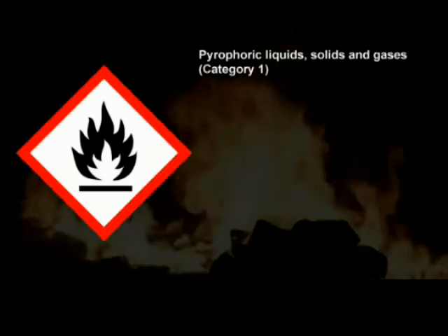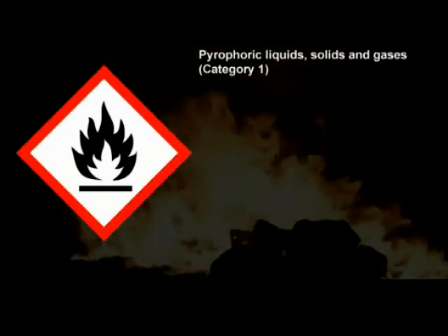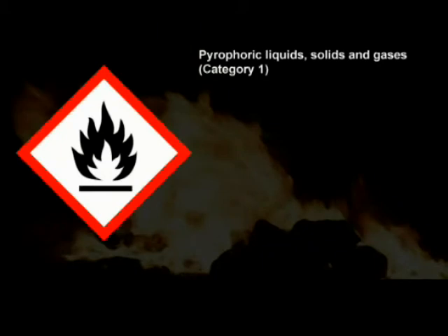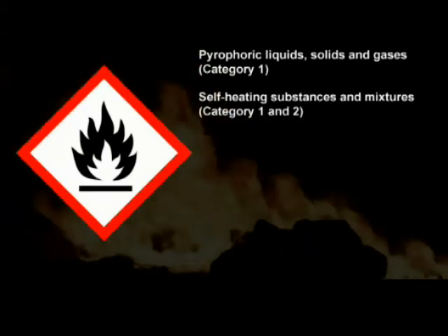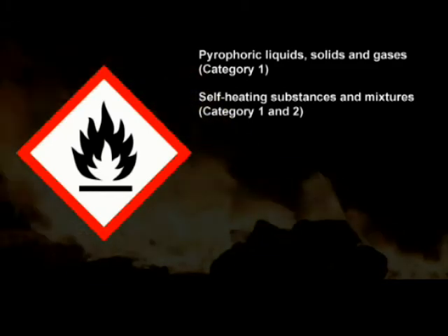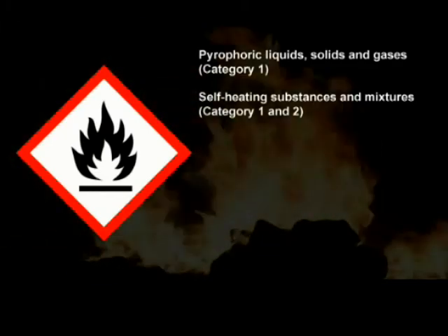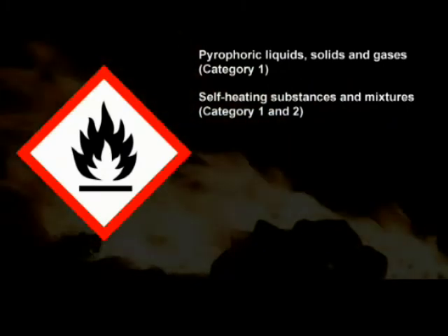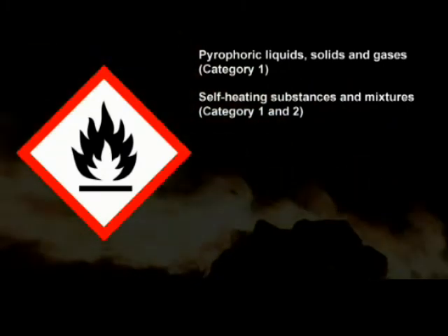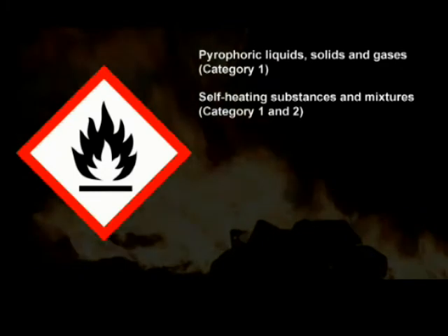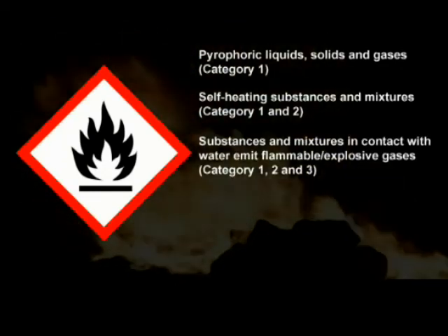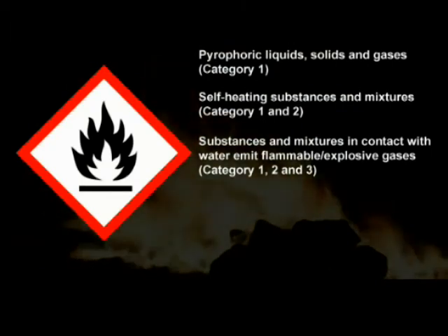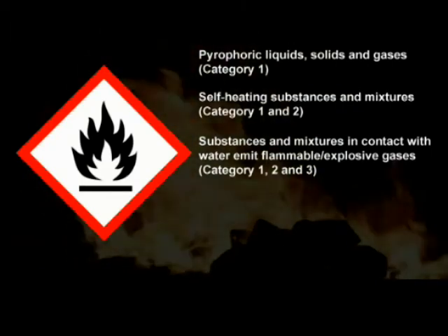or explosion. Pyrophoric liquids, solids, and gases, Category 1. These products can catch fire very quickly, spontaneously, if exposed to air. Self-heating substances and mixtures, Category 1 and 2. The products may catch fire if exposed to air. They differ from pyrophoric liquids or solids in that they will ignite only after a longer period of time or when in large amounts.